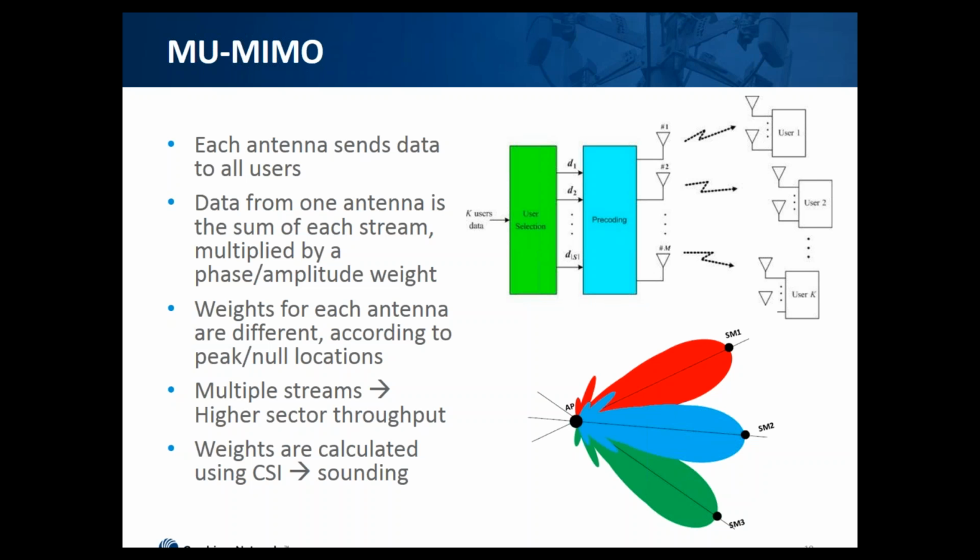We talked about the fact that the access point can send data to multiple users or group multiple users in the same transmission. But can any user be grouped with any other user? Or are there some restrictions the scheduler needs to follow when forming groups? Let's imagine that user 2, the one in the blue beam, is very close to user 1, the one in the red beam. In order for the access point to send data to both, the two beams, the red beam and the blue beam, must be very close to each other, almost overlapping.